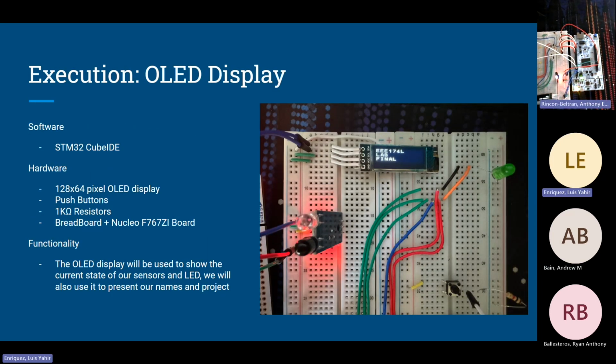So for the OLED display, I decided to go with the SSD 1306 drivers that were shown in one of the extra lab handouts. I used a 128 by 64 pixel OLED display, and it was pretty simple to set up. You just provided some power, a ground pin to it, and then the actual signal, or the connectivity pins, are through the SCL and SDA pin, and you just set that up in the STM Cube application in the connectivity settings, and then that way you're able to interact with the drivers, choose your font, choose the font size, and then place exactly where you want to place your text.